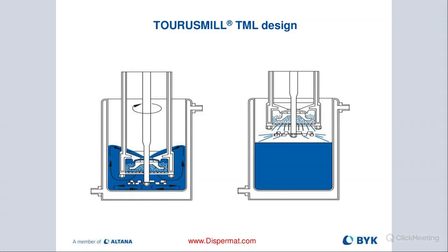If you want to do a fine cleaning, there are a couple of screws on the bottom, these Allen screws, that you remove, and then you're able to remove the screen, and the beads drop out. You can catch the beads in a pan on the bottom, and then clean them with the sonic bath, which always works well, and then do the fine cleaning, the fine touching of the components once you open it up. But it's relatively easy.